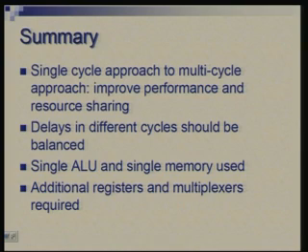Similarly, while resource sharing, we have eliminated those adders and we have eliminated one memory, but we have incurred extra cost in terms of registers and multiplexers. Okay. So, you are sharing, but there is an overhead of sharing, and we have to be a little more careful in our calculation and ensure that the overhead does not overshadow the gain.